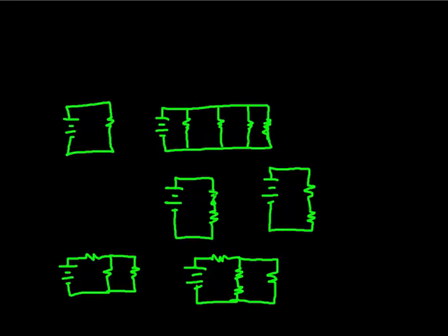Here, this gets interesting. It's a tough drawing, but there's a node here in the middle. In other words, there's 2 resistors, one on top of each other. What you know here, if this is 12 volts, is that there's 12 volts sitting right here, and potentially 0 volts sitting right here. 0 and 12, that's how a battery would work, 12 volts of potential across it. So from here to here, if you put a meter, there would be 12 volts. But what you don't know is what's sitting right here in the middle, and that's what we're going to cover in the next section. I'll do the same thing again here. You could have 120 volts here, and the difference in potential between these two would be 120 volts, if that makes sense.